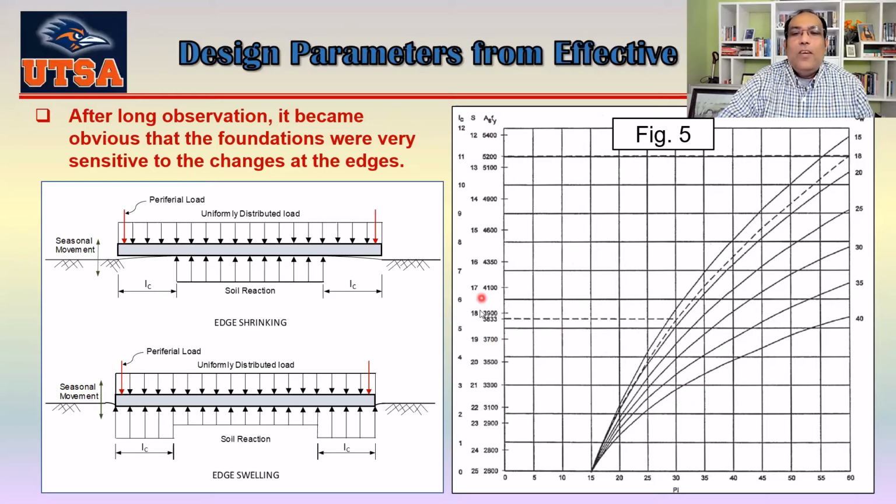So from there, you can also see they are giving you the S. S means the spacing between two stiffened beams on the slab. Okay, the maximum distance you can have, that's actually your S. And you have also ASFY. This one also gives you your reinforcement design for the slab.